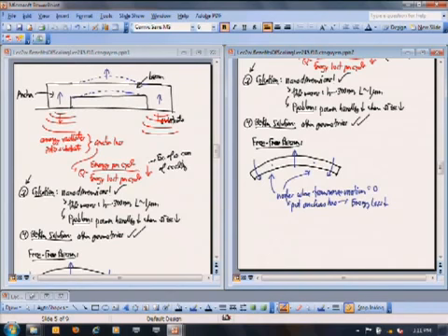So this actual design looks like this from a top view. Okay, you're sort of holding it up that way. And so there's no motion going up and down, but these things are going into torsion here. You still get torsional motion of those supports, and you have to design against energy losses.